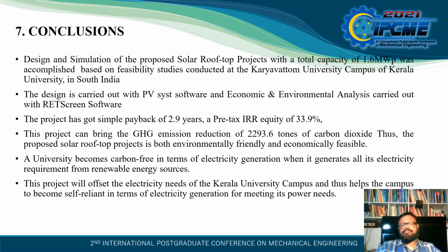The project has a simple payback of 2.9 years, a pre-tax IRR equity of 33.9%. This project can bring GHG emissions reduction of 2,293.6 tons of carbon dioxide. Thus, the proposed solar rooftop project is both environment friendly and economically feasible.